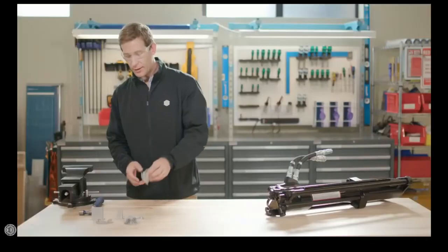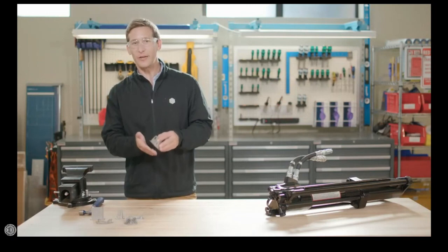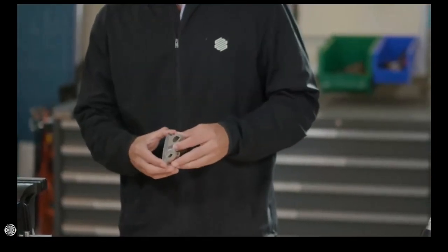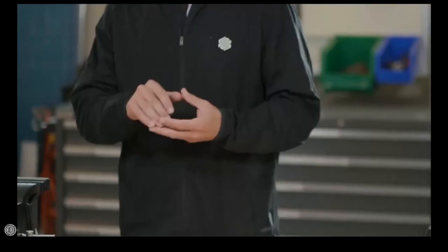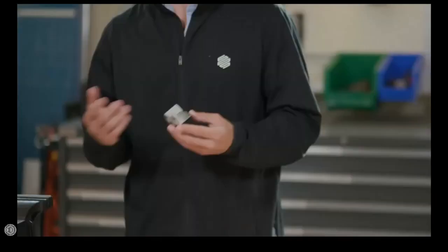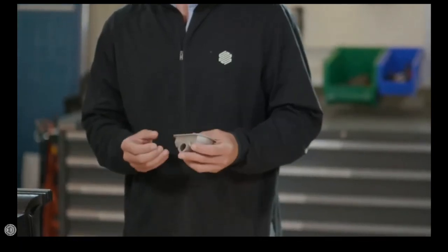In the furnace, the layer of printed release material between supports and the raft and your printed part remains powderized. This allows the structure to be tacked to the raft to better control shrink and accuracy throughout the process, but also an easy release after sintering.